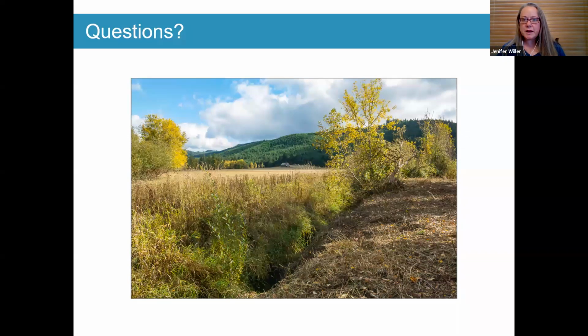The first one happened when you were talking about modeling, and Gary was asking about how well the hydraulics model is coordinated with geotechnical. He talked about an experience of the hydraulic modelers sometimes saying they have critical scour when it's solid rock.